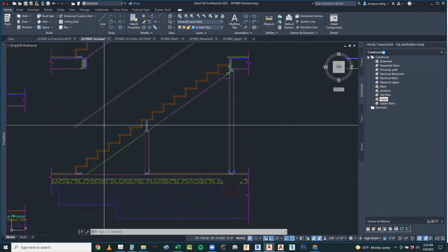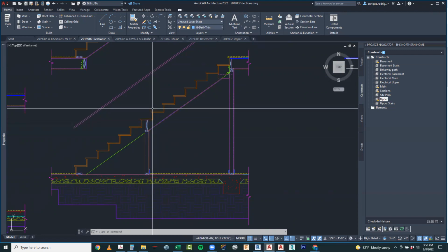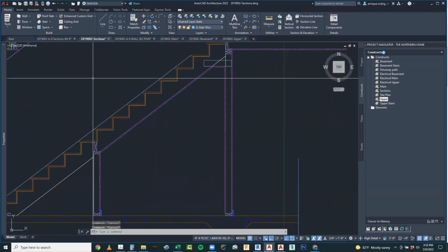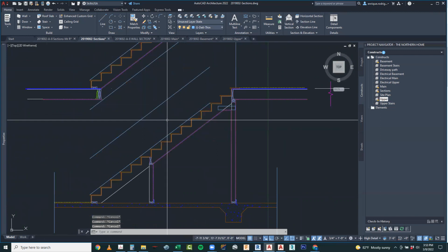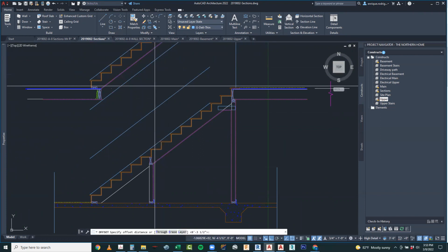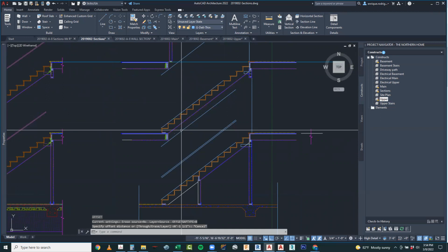The next thing that we can do is we can always offset this. Again, if you look at the book and the section, the typical height for the railings is about 34 to 36 inches from this same line right here that we did. So I can copy this guy. Let's put it at 34. And let's make it about 2 inches. So this time I'm going to go ahead and offset 1.5, and that's going to be my railing offset, and I can just copy this guy up.